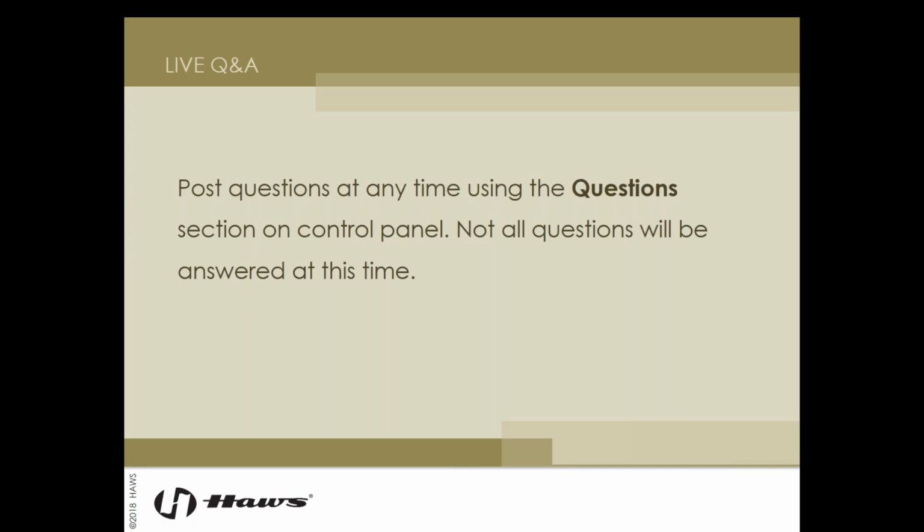Perfect. Mark wants to know, do offices or places of business have to have a drinking fountain, or is a water bottle dispenser okay? A water bottle dispenser does not replace an ADA accessible drinking fountain. The ADA specifically describes the drinking fountain. It has to have a bubbler head that's not higher than 36 inches above the finished floor. It creates a stream that's 4 inches high so that you can insert a cup underneath it. It has to have knee space underneath it and protrude 18 inches so that you can slide your legs in a forward approach.